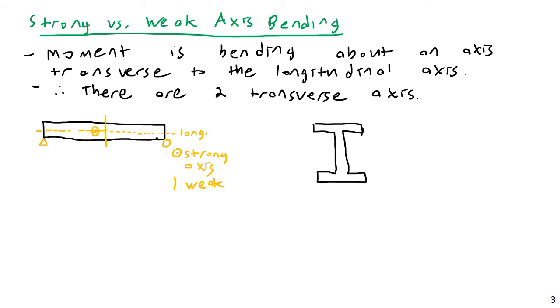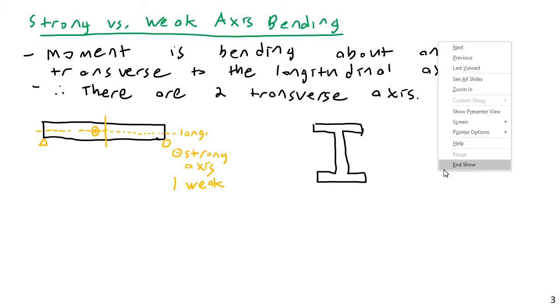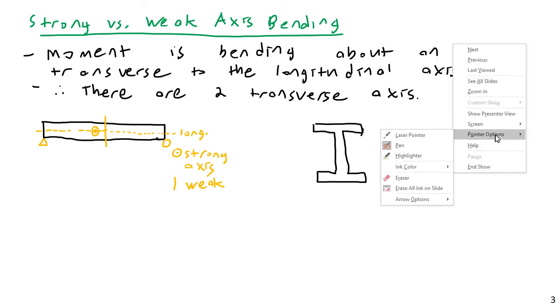Can you tell me, what is the logic behind a W section? Why do we design it, why do we lay things out like that? Exactly, yes, very good. The area moment of inertia, especially on the strong axis. The entire logic, and we'll see this more through the semester in steel and concrete design, is to get as much area as far from the neutral axis or the centroid as possible, because that is what gives you your bending moment capacity. So you want lots of area far from your neutral axis, and that is really why a W section is laid out the way it is.